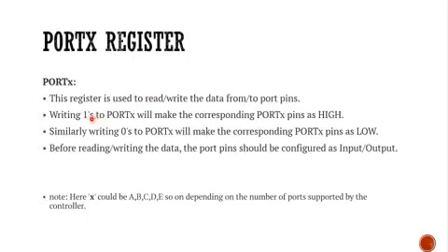So how do we do this? By writing one through program, through C program. So this means that by writing one to the selected port, it can be port A, it can be all the port. Okay, let's say if we want to use port B, we write 1 to port B. So this means that the port output will produce 1, logic 1, okay, or around 5 volt.